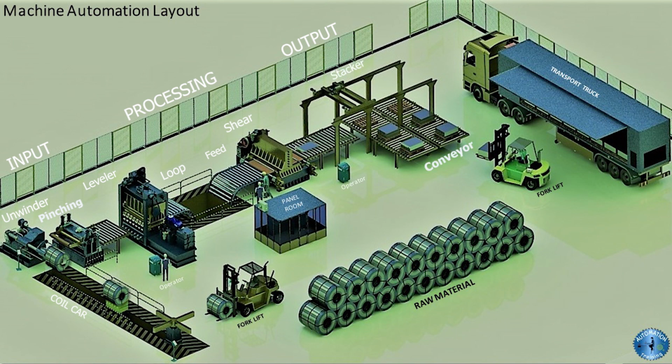Concerning each section, it has its operating equipment, which gets driven with the help of electric motors and solenoid valves operated by hydraulics and pneumatics. Every control has various sensing devices such as proximity sensors, photosensors, ultrasonic sensors, limit switches and others. All those devices have electrical connections as per manufacturer design specifications, which we need to see while wiring those in the field or control panels.